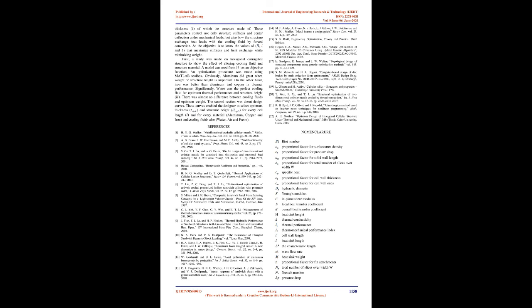Using water with aluminum structure would reduce total weight by 20 and 40% compared to freon and air respectively. In case of copper structure, water reduces structure weight by almost 30% compared to both air and freon. And in case of iron structure, water would reduce weight by 40 and 50% for freon and air respectively.